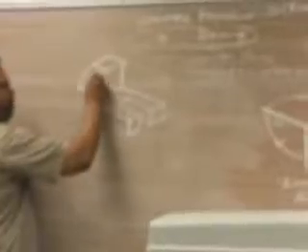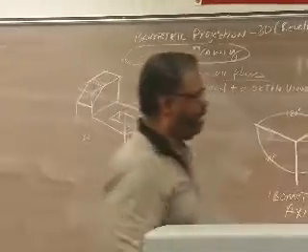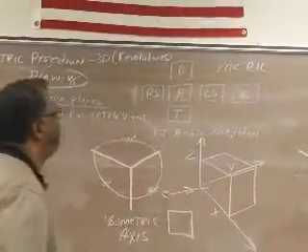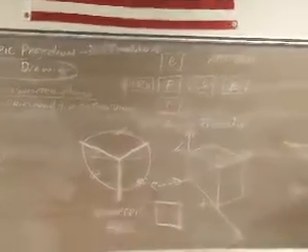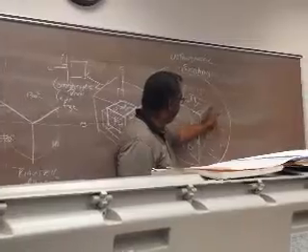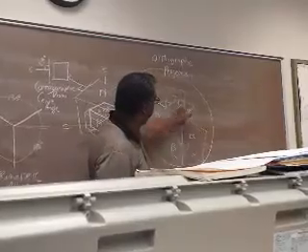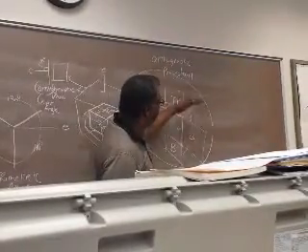This plane right here is your front. Here's your top, and so forth. So again, if we just had a cube here, and we unfolded it, then we would get the third angle projection arrangement, and then when we fold this back up, this is an isometric plane. This is an isometric plane. This is your isometric plane. So my 6 principal views correspond to my isometric planes.